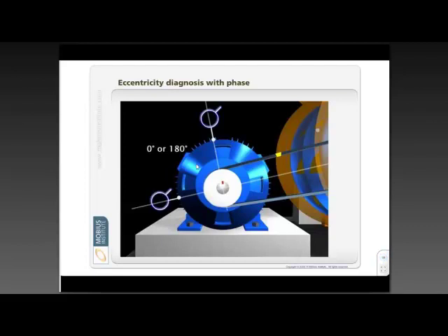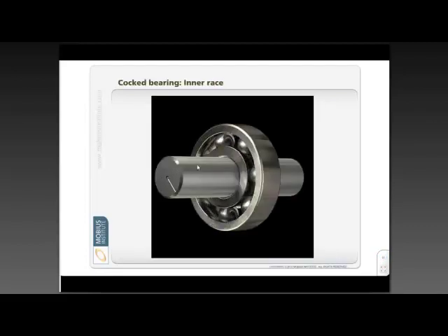Hard to explain in a short time, but that's what we see. With misalignment, we don't see a 90 degrees phase relationship either, mostly just with unbalance. If the bearing wasn't installed properly and was cocked on the shaft, that motion that we can see, again, it's exaggerated, but it creates axial vibration and a certain phase relationship. We'll see that it's out of phase.